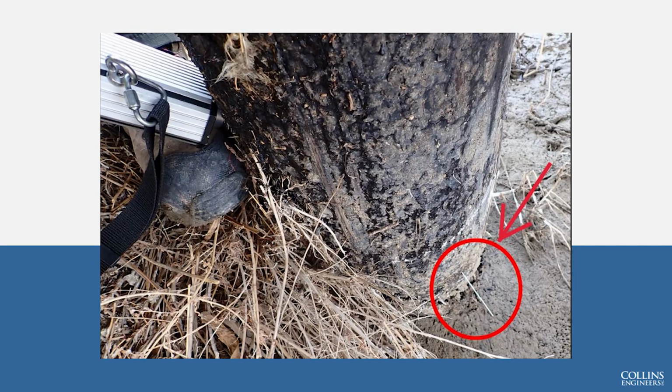Added this slide in here. If you look on the left, that's the drill, and on the right, it actually did a full 90-degree turn and came out the bottom. Definitely something that an inspector has to be cognizant of in the field. You can get basically false measurements if it follows the wrong angle. You can think the pile's not the right size or the defect isn't the right size, stuff like that.